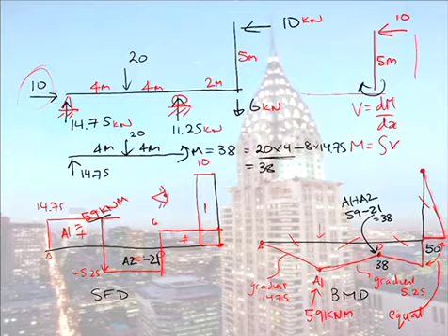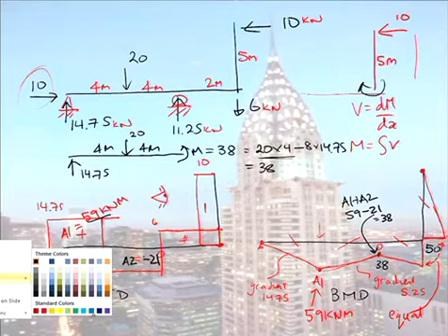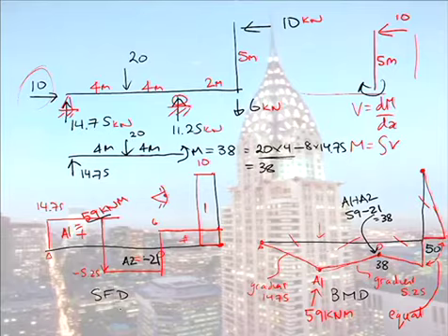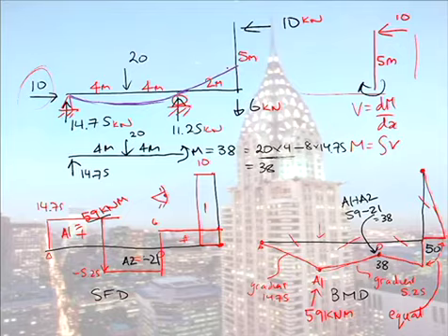What I didn't do here, and somebody pointed out, is what the deflected shape looks like. I wouldn't have attempted the deflected shape until I got my bending moment diagram, because it tells me I have tension on the bottom throughout this beam and tension on the outside. So in order to get that, I'm going to come sideways to draw it nicely. This thing must be deflecting, and when I draw deflected shapes, I draw them very exaggerated, of course. We're talking just a couple of millimetres of movement normally. So tension on this side, tension on the bottom throughout.